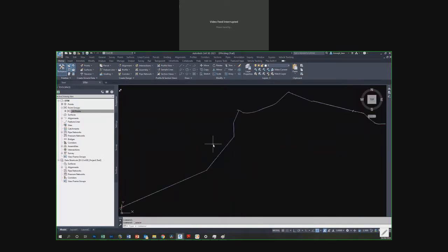And you need to remember that you need to save your drawing quite a bit. Get a habit of pressing Control and save, because sometimes Civil 3D closes by itself without giving any error or warning or message, due to the limitations of the hardware. If the hardware gets stuck, Civil 3D just closes itself.